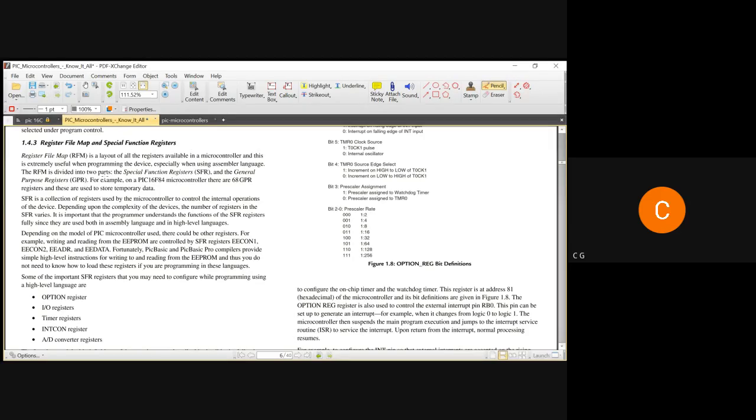Okay. You write the scale on the x-axis, voltage, and on the y-axis you have current, so an IV characteristic can come out. Whatever the maximum range is, you first choose that, and then accordingly you start from 0 to the maximum. So 20 lines, 20 centimeters equal to this and this.